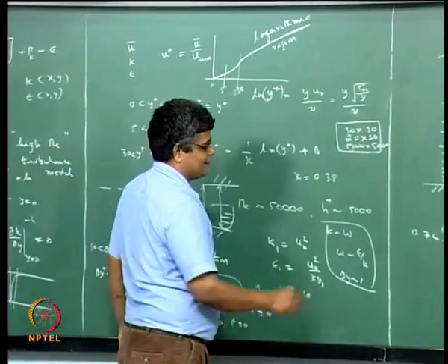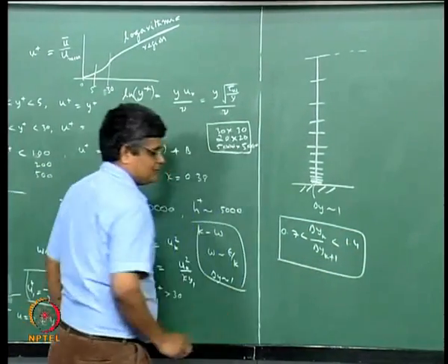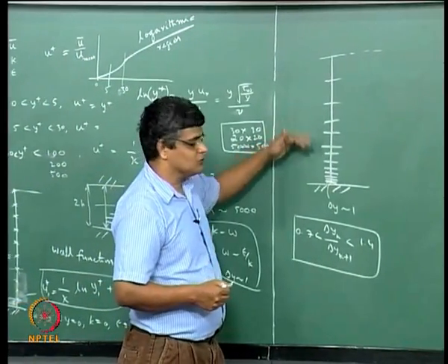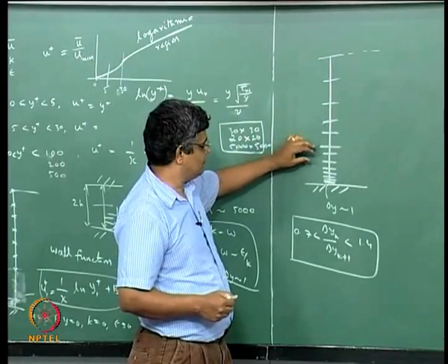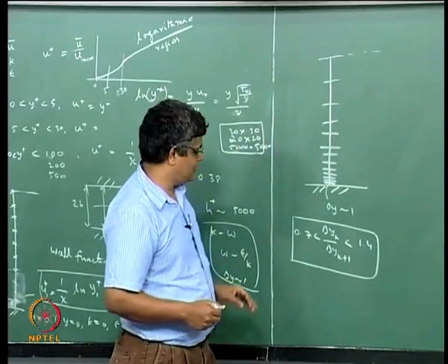That is a general thumb rule, so as not to lose too much accuracy of the finite difference approximations when we have this sort of expanding grid.